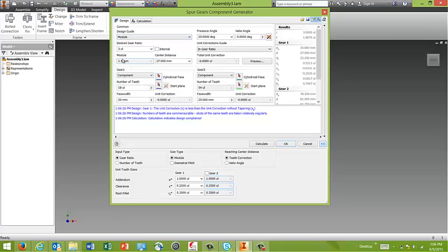And what happens is that if you are 3D printing your gears, I would recommend you to 3D print modules 1.5 and greater, because for 1.0 the 3D printers don't do a very good job in it. Okay? From here you can check. Very importantly is your gear ratio, your desired gear ratio. I can change it to 2 and I can calculate it.